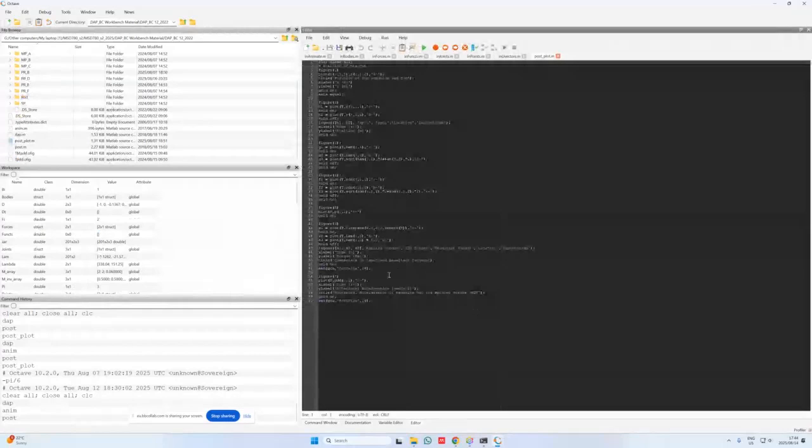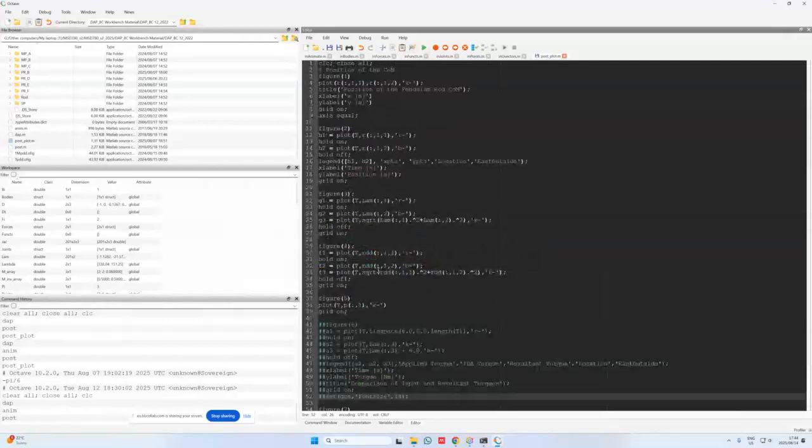In this case, we're just not going to consider Lagrange multiplier 3 because we don't have a Lagrange multiplier 3. Remember that the only two Lagrange multipliers that we have in this case are the X and Y reaction forces associated with the revolute joint. We don't have a third Lagrange multiplier because that would apply to a driver constraint that we specify, the relative rotation driver. So I'm just going to switch this off in the script.